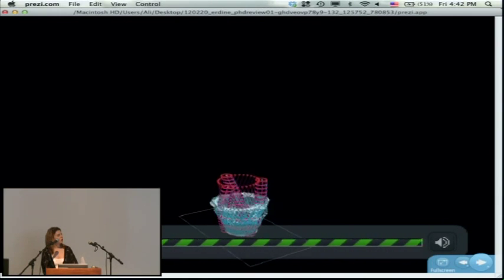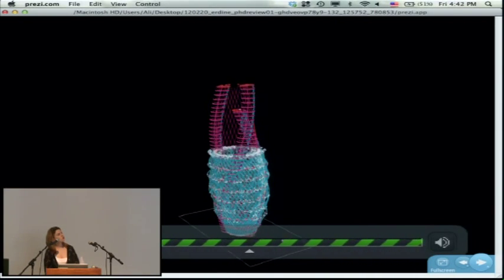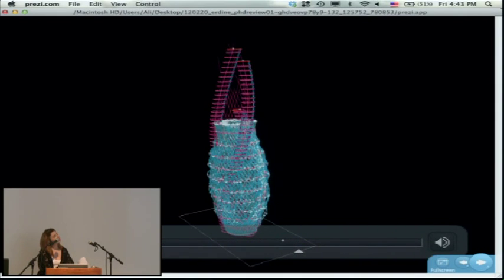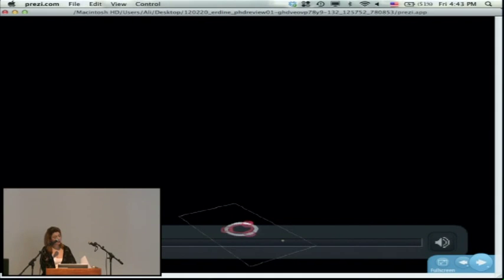So the next step would be, after generating the framework, which later on could be the load-bearing structure, how to start to integrate the load-bearing structure with different subsystems such as circulation or facade systems. So this is one study where I am actually starting to form a structural framework, and then the structural framework gives also the information to generate a circulation system that is generated around the tower facade, and then another hierarchy that makes the facade system.